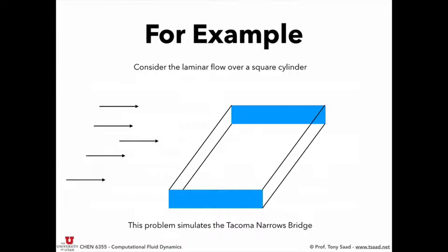Yes. So you remember the von Karman Street, the flow over the cylinder? So at a certain laminar Reynolds number, the flow is going to develop vortices behind an object, okay? And in fact, it's going to develop what's called an alternating pressure gradient. So the pressure is going to alternate positive and negative, positive and negative. And it's going to cause this vortex shedding that's going to cause some frequent change in the direction of the flow behind the object.